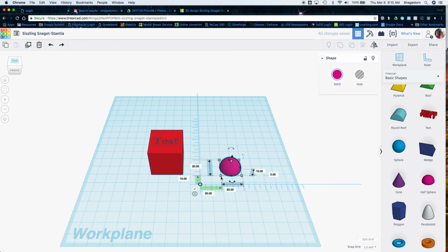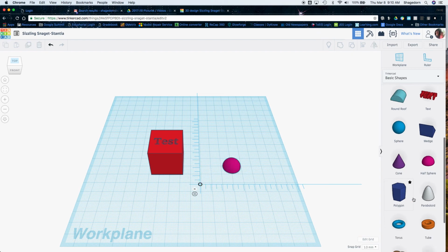If you click on one side and hold down Shift when you do this, everything will be the same dimensions when you size it. So it keeps those basic dimensions so everything is scaled properly. So holding down Shift is going to help you out tremendously when you go through this.